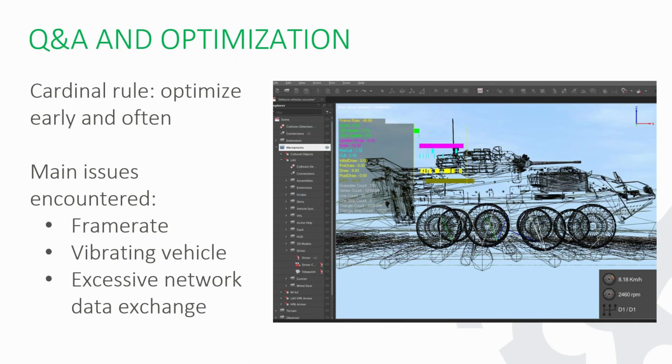So we used the profiling tool to get an idea of what was going on. The physics was running fine. There was no delay at all. The CPU was supplying all the horsepower, so the problem wasn't there. So we dug a little further. We went into the GPU and started looking at its load, and we realized that the GPU was quite overloaded. We were using 4 gig memory cards, and the actual memory footprint of the simulation was 4.7 gigs, which means that swapping was taking place, which would explain the low frame rate.